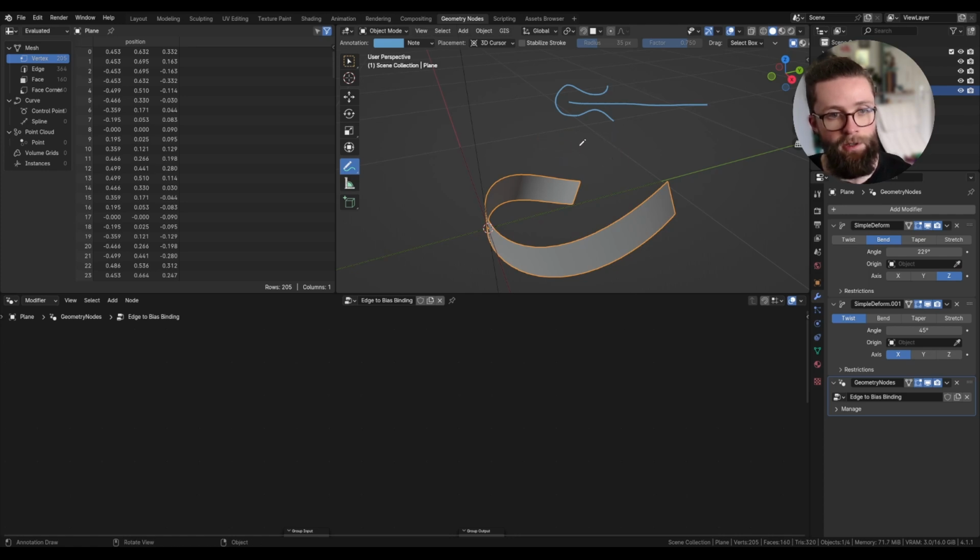And to do this, here we are going to generate a curve that will look a bit like this. Two curves on one side, duplicate them on the other side, and then we'll join everything with other curves. That way we'll have control over the fold position right here, in between the two curves we will create at the start, and by adding fillets on the sides, we'll be able to have this kind of shape really easily.